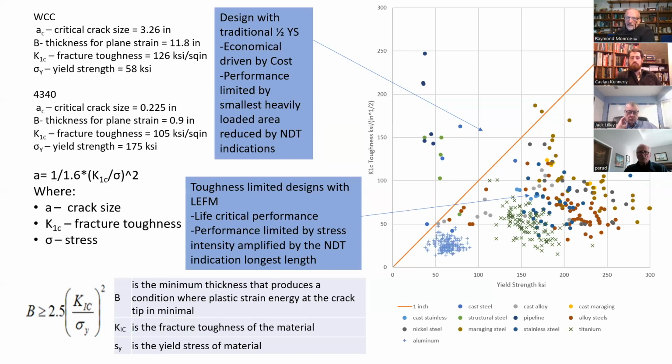If, on the other hand, you had a brittle material, a really high-strength, low ductility material, what you had to do is pretend anything on the surface or anything in the microstructure could act like a crack. And the life was determined by how rapidly the crack grew.